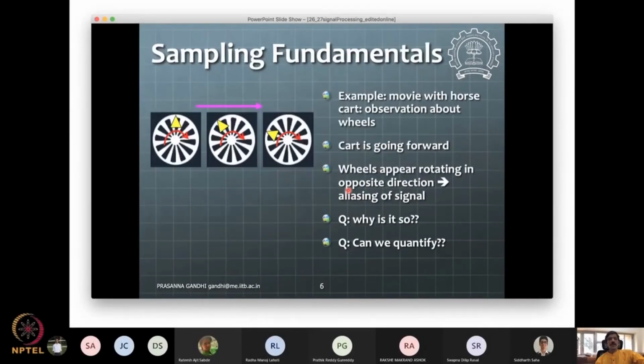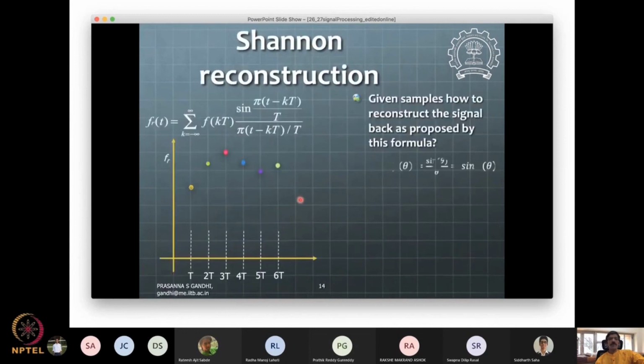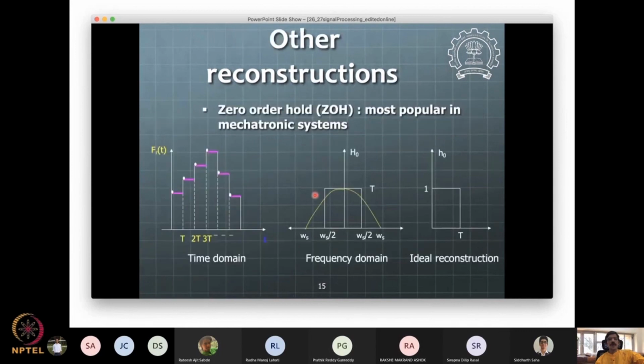Okay, so far we have seen this kind of signal in the frequency domain, and now we'll see its effect on the system. So one can ask a fair question. If we are saying the Shannon reconstruction reconstructs the signal back in the frequency domain by using this kind of a filter, where T is a scale for the signal, it is like an ideal filter. It's a rectangular filter, which is a sharp cutoff kind of filter.